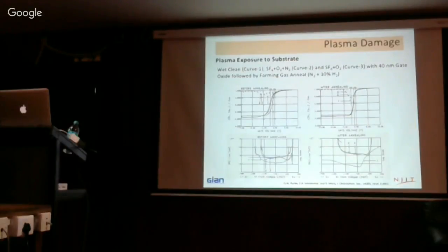And one more thing, for this aluminum contact, is there any effect while making the contact at the interface between the dielectric and the metal contact? Typically, if you make aluminum contacts, there should not be much difference. But if you do not anneal just after depositing aluminum, there is a barrier that forms. Then your accuracy of measurement goes down. Because aluminum's barrier height is 1 point something, like a Schottky barrier to silicon.